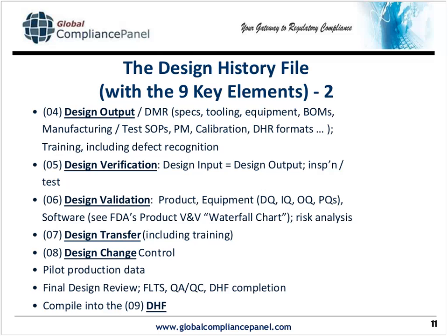Design validation, that's the sum total of all the verification steps. And again, we'll see that by means of this chart that's mentioned here, and I have a slide of in a minute. Now, design validation includes the production environment as well. So you're getting into not only product validation, but the process validation, which gets into design qualification or specs, the requirement specs, your installation qualification, the operation qualification, your performance and process qualifications. And those are more than one. They're usually 3 or more, depending on the amount of effort necessary to address all the worst case inputs.